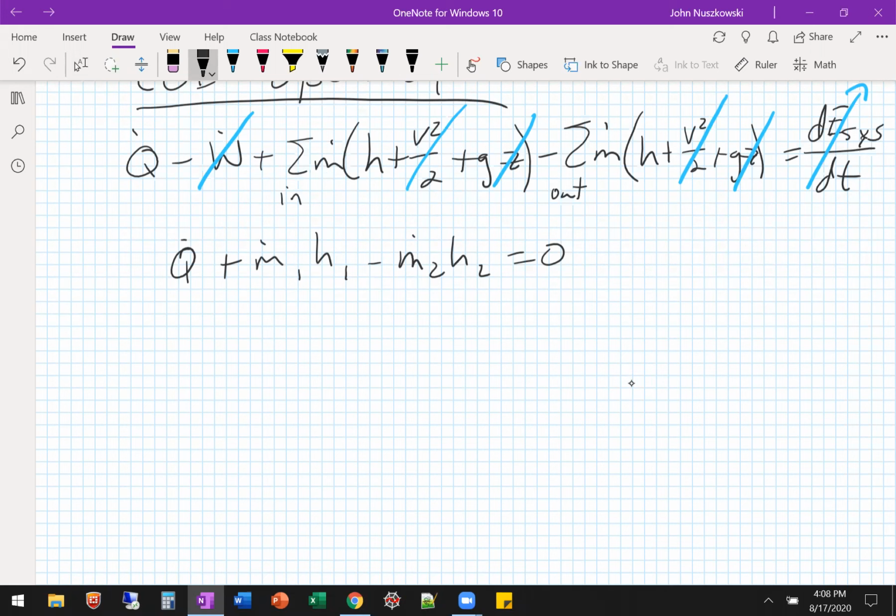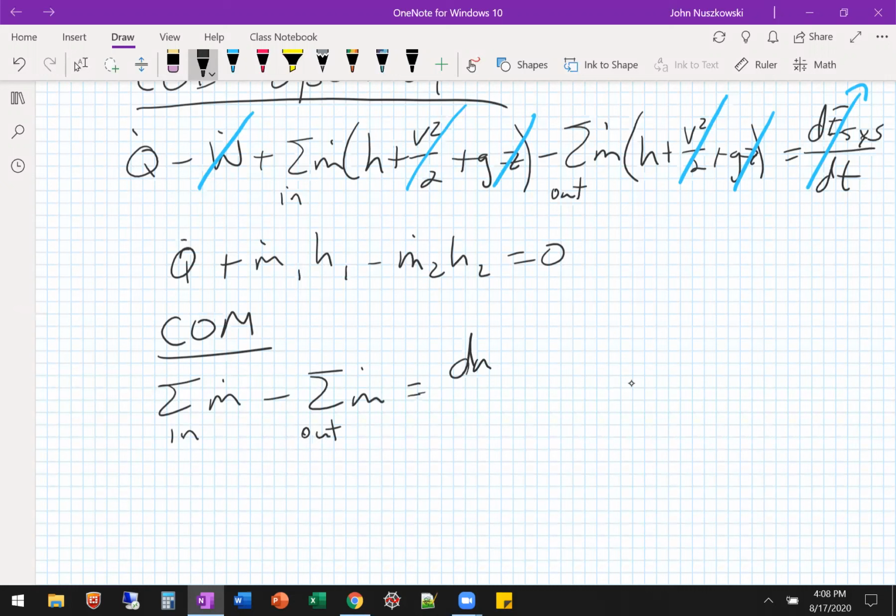Mass flow rate 1 and mass flow rate 2 are the same. Yes, so from our conservation of mass, it's again steady state, so there's no mass change. The amount of mass inside the system is not changing with respect to time. We're not filling, we're not emptying. We only have one inlet and one outlet on that boundary. So mass flow rate 1 is equal to 2. We can also look at it and do mass flow rate 3 is equal to 4.